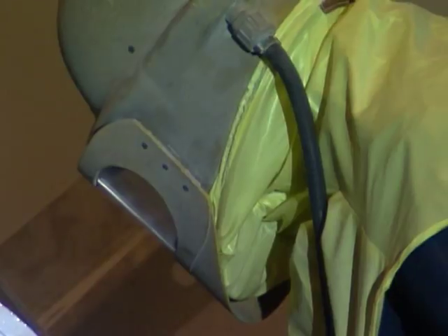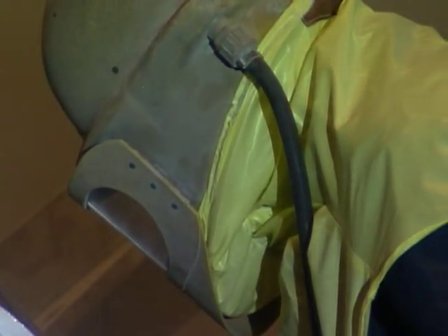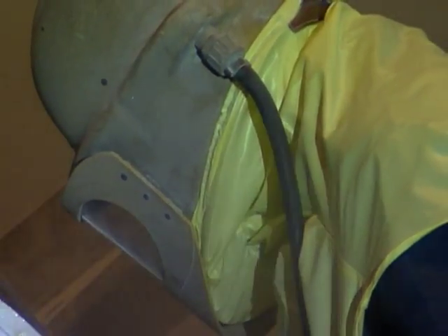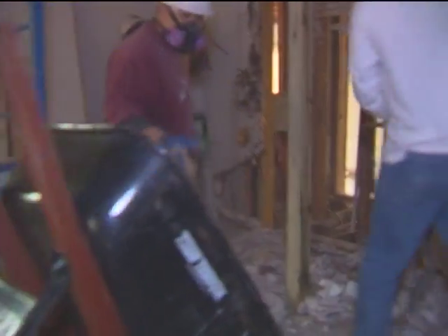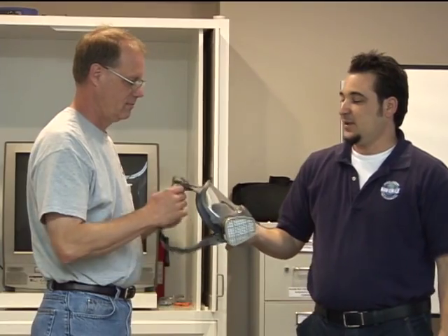Among air purifying respirators, powered air purifying helmets have been subjectively rated the best for breathing ease, skin comfort, and in-mask temperature and humidity, while filtering facepieces are rated high for lightness and convenience. Each, however, has its own drawbacks, and all factors should be taken into account during selection.